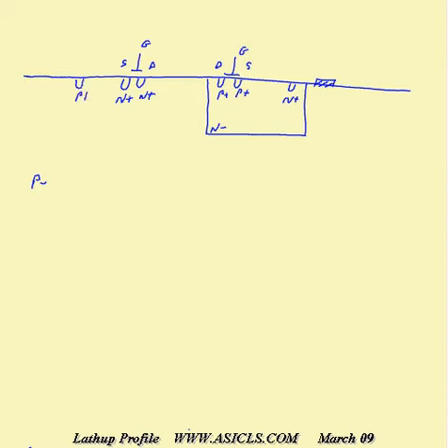Here we're showing the P+ implant, which forms a good contact to the substrate, and then we'll use again some metallization, which we'll use to connect VSS via the P+ P-tap to the substrate so that the substrate is tied low. So let's connect the N+ implant to the lowest metal, metal 1, and also connect metal 1 to VDD.